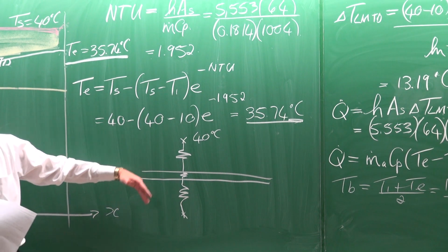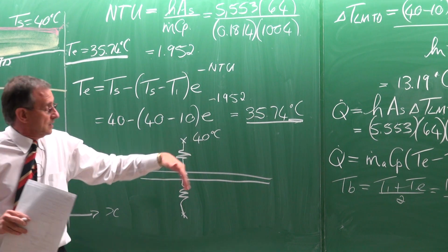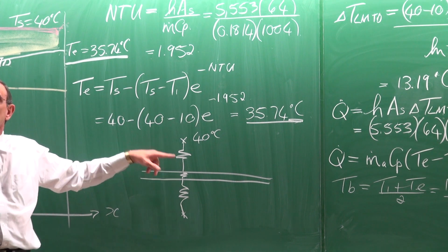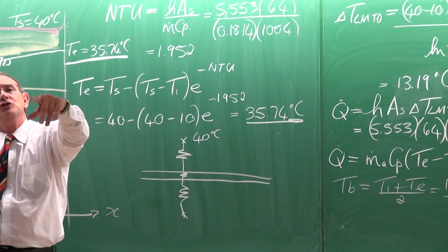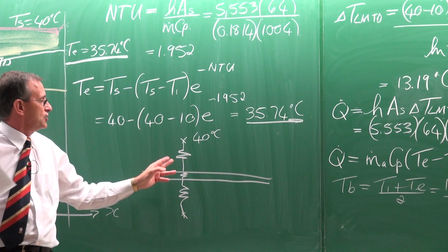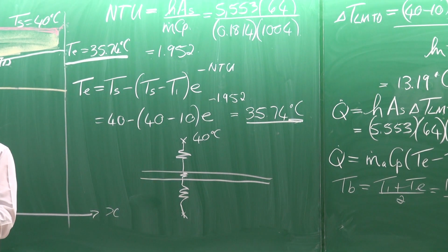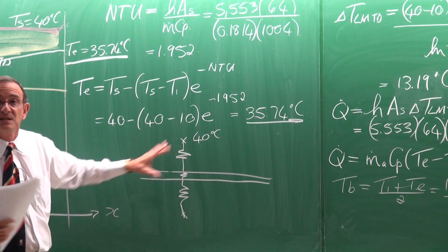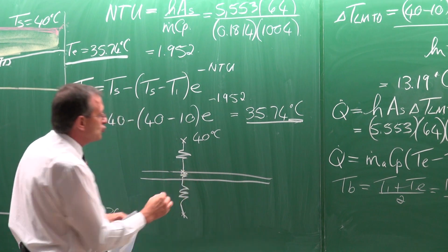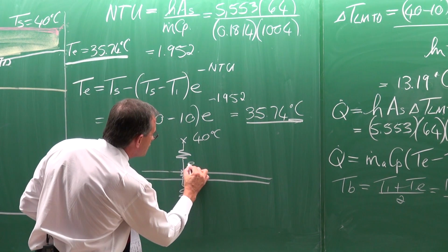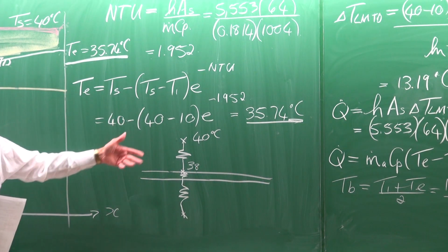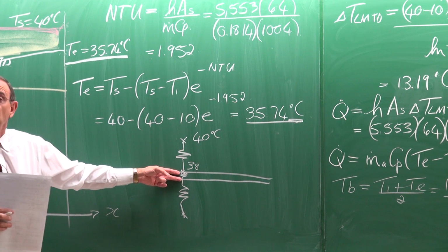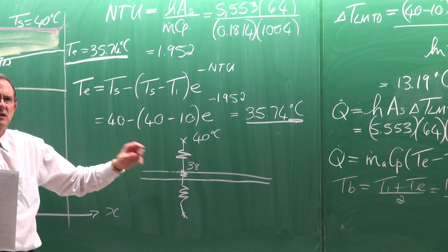Okay. So the correct thing in this case would be to take that temperature, to get the heat transfer coefficient up there, which we're going to do in the next chapter. The heat transfer coefficient for natural convection. You haven't done it yet. You can maybe in the meantime assume a value of 10. Then you can calculate that resistance, and then you can actually calculate that correct temperature there. Now let's suppose it is 38. What normally happens with the material here is that normally these ducts are made from galvanized steel, galvanized plate, and they are very thin.